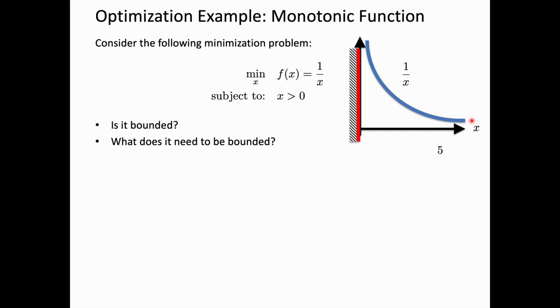This is an important concept. But when it comes to engineering design optimization, just simply adding a bound often is not a good strategy. It's usually the case that we've overlooked something, and so instead of adding a simple bound on a variable, it's good to find something such as a failure mode that we might have overlooked that is capable of bounding our problem. So specifically, if we add this bound, x must be less than or equal to 5,